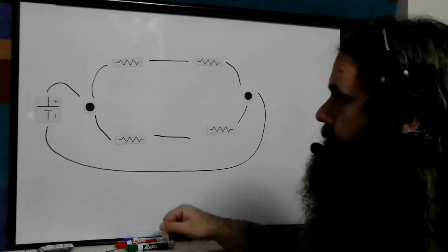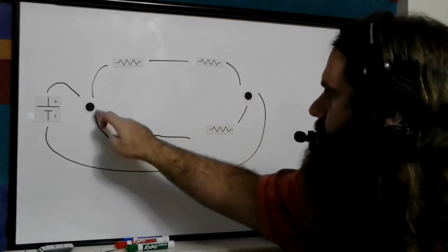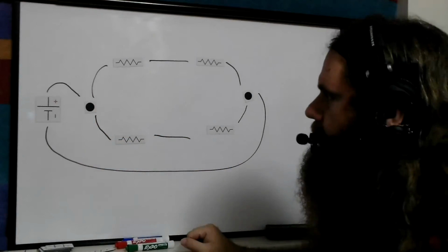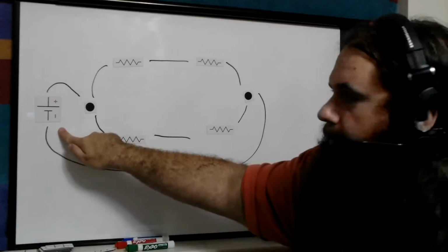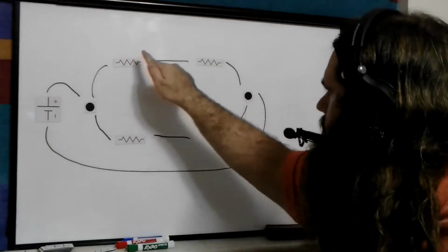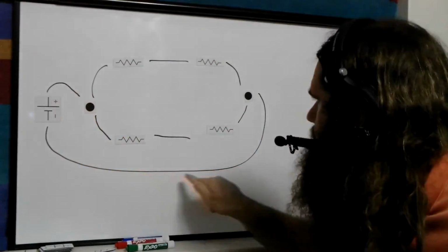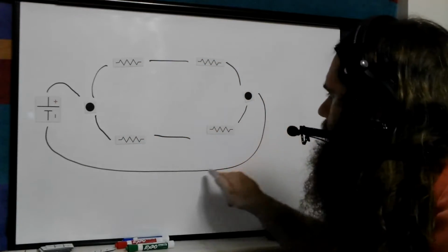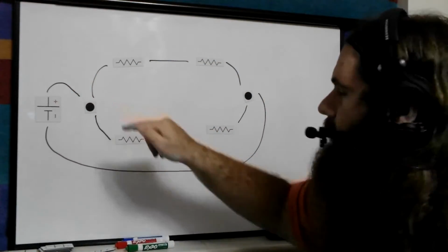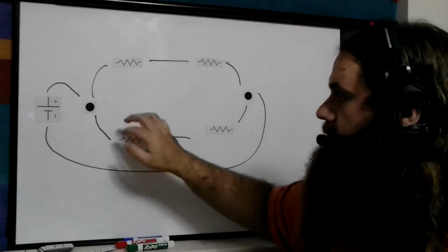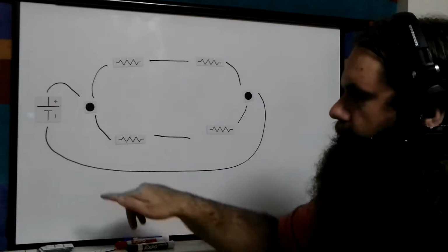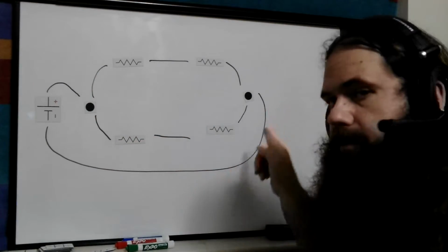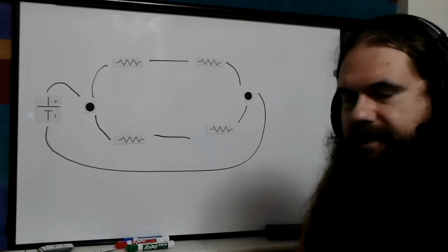But you can also do other loops. You can do a loop here, ignoring the power source entirely. You can do it twice. You could start at the battery, go here, and around, and back through the battery, and around this way, and back out, and back to there, if you wanted. As long as you don't double back on yourself, don't reverse, just keep tracing a line through junctions, and end up where you started. That's it.